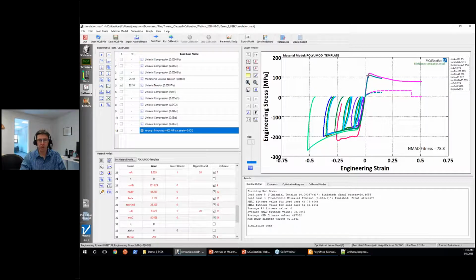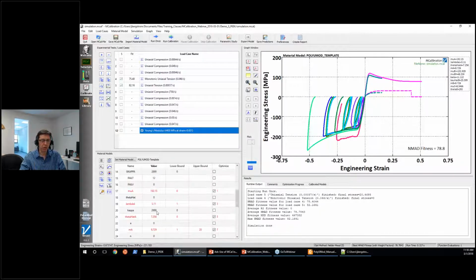If you look at this graph, in tension I don't have the strain rates really shown here, but it clearly looks like this material yields in tension at a stress that is lower than the corresponding yield stress in compression. And that's something you can capture in this model. There's a parameter to control that here, the A parameter. So that's the beauty, right? You have to have that information though to find out how this really works.